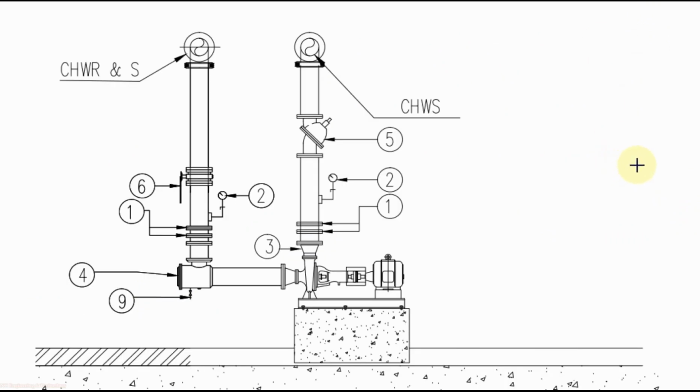For chilled water pump hookup or wall package, we use two types. If you are using a suction diffuser and triple duty valve, then you can have the minimum number of valves. Here in supply only you need to provide the triple duty valve, and in return you can have one butterfly valve and suction diffuser. Here you can use a flexible coupling or pipe flexible joint.